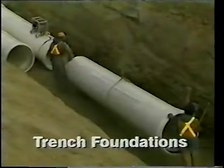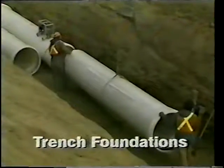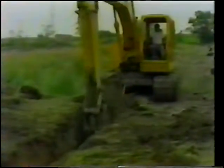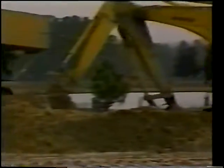If the native soil is to form the trench foundation, it must provide stable, uniform support for the pipe. Organic material, or soft or low-density soil along the line, can cause unequal settlement. Very soft, wet soils can be replaced or reinforced by working in drier or stronger material and compacting well.